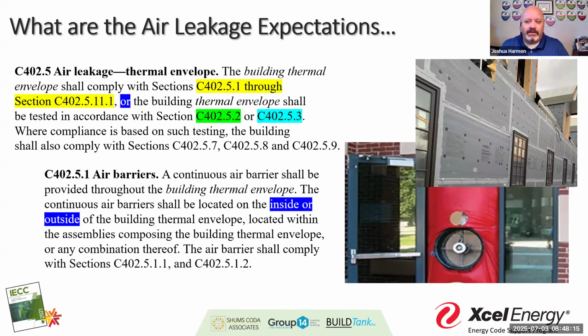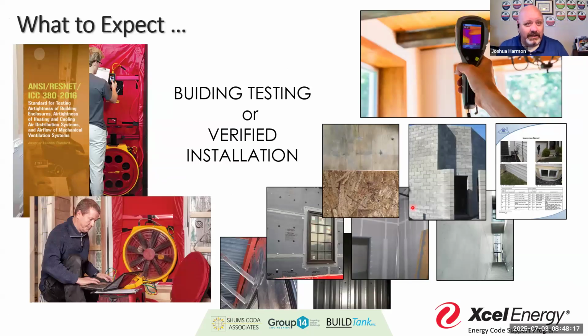And then again, it's likely not going to be the building inspector, because the building inspector is there for spot inspections. He's not going to look at every assembly and verify that every seam is done properly. And again, thermal smoke trace, we've talked about that in the past. We'll talk more about air barriers and the methods of installation verification as we go on.